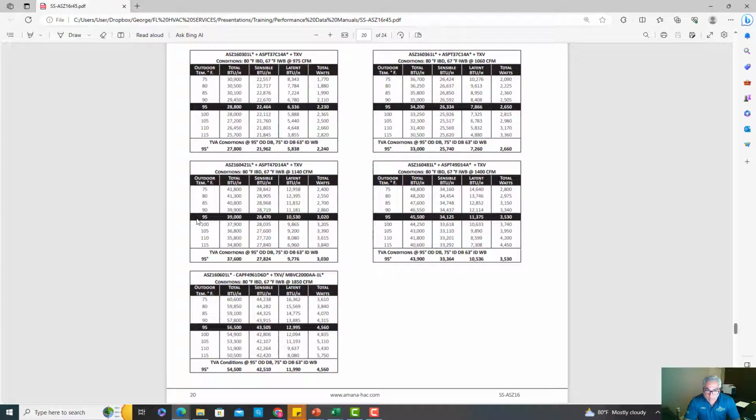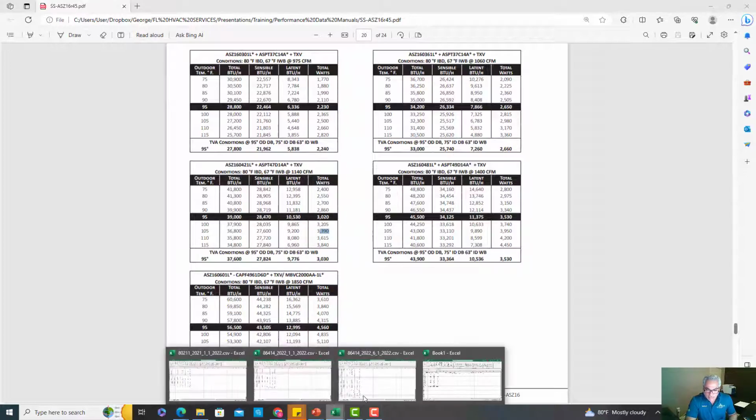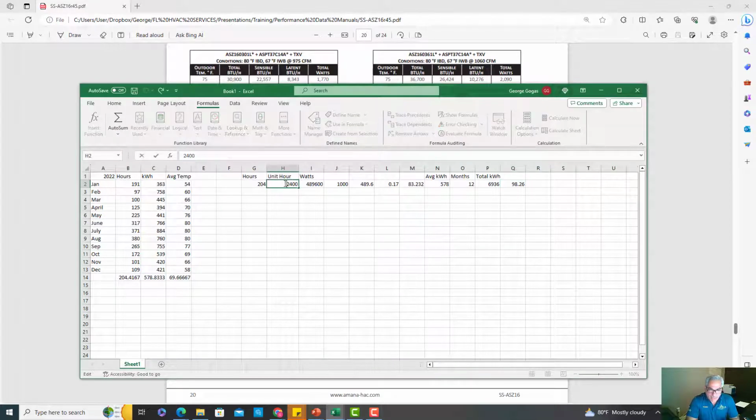Now, and this is supposed to be for a unit that is 100% clean, operating correctly. So what makes it work harder too is not only the heat, but dirt. If your evaporator coil is too dirty, that's going to make it work harder. So if it's working harder, you're pulling in more, right? So here, let's go for example here. If I took my unit hourly to 3,500 on a bad unit, my electric bill goes from 80 something to 120, right?